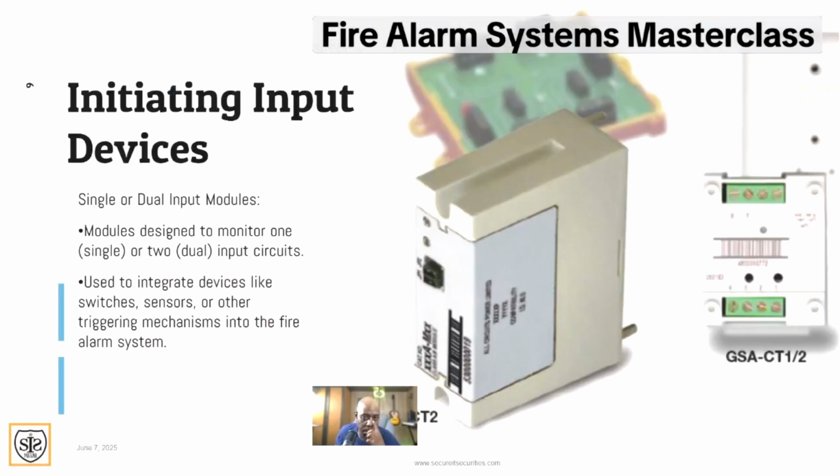These are typical initiating devices. Here you would hook up non-intelligent fire alarm devices like a tamper switch, a water flow, anything that cannot directly connect to the fire alarm control panel. So usually a supervisory signal, like I said before, a tamper switch and a water flow, or maybe a non-coded pull station, a non-coded CO detector. So anything that's non-addressable, that's not made by the manufacturer, you can connect it to an input module, so that module could then either go into alarm or cause a supervisory, or whatever the point type is, or whatever it is you're trying to do with the fire alarm control panel.